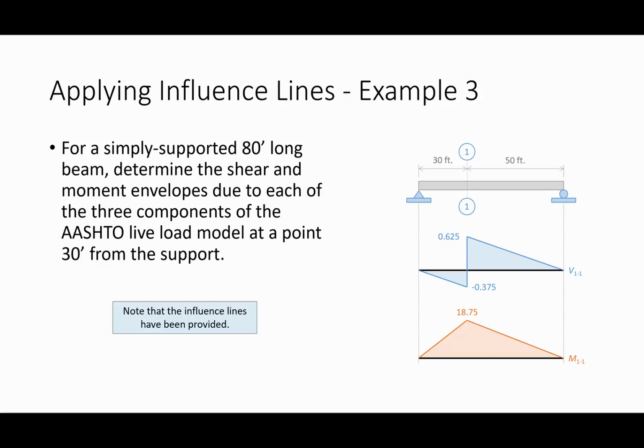So you notice on this problem, we're doing a real world application with AASHTO provisions, but I don't have a beam that has hinges and fixed ends and all these crazy boundary conditions. I'm keeping the bridge simple and practical, and I want to go through the real world aspects of how you would do this. Now I'll go ahead and tell you that most software programs will do this automatically, but I want you to understand the output when a software program spits it out, what values it's producing, what those values represent, why some values are 0, some values are not, and that'll be my focus here. We have a simply supported beam that's 80 foot long, and I picked a random point on the beam. So we picked this point right here, this point that's 30 foot from the left support.